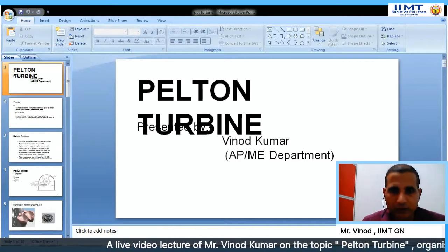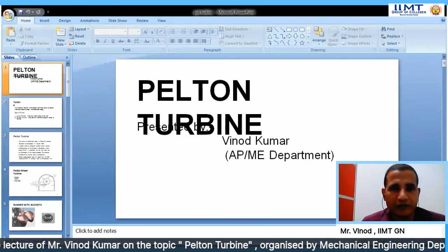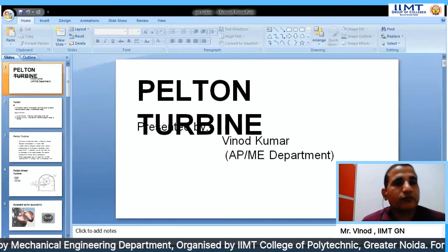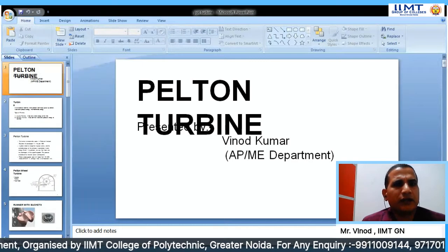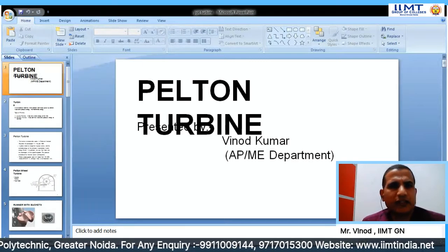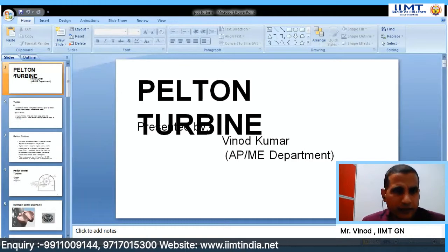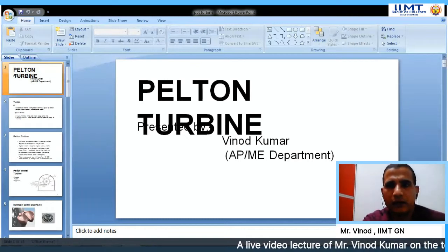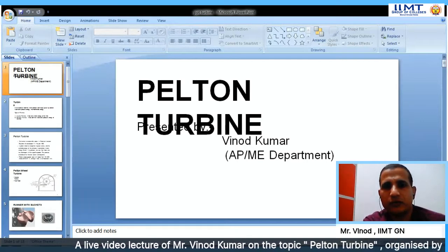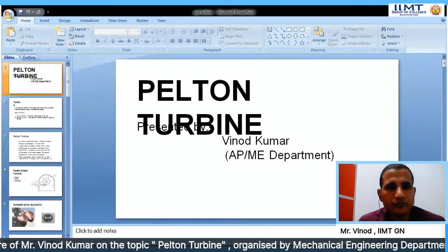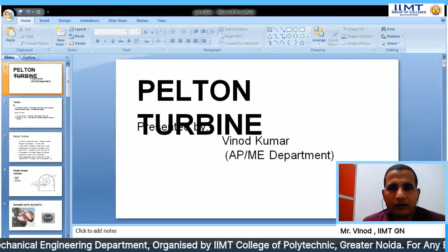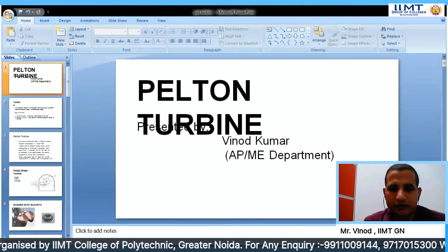It is covered by the casing. It is not changing every time. So we can say that it is the mass flow rate into the acceleration of the system. Now this is the working mechanism. The high-speed water jet emerging from the nozzle strikes the bucket at the splitter placed at the middle of the bucket, from where the jet is divided into two equal streams. These streams flow along the inner curve of the bucket and leave it. So these streams rotate the runner, and the shaft also rotates.